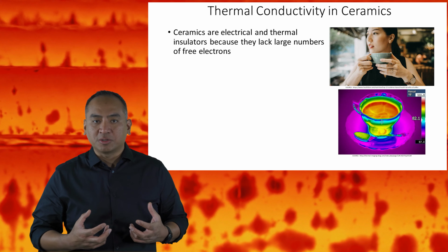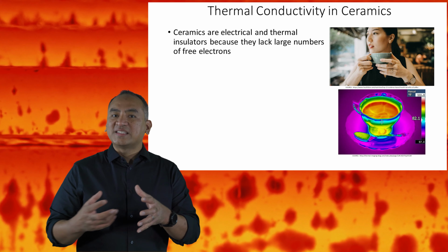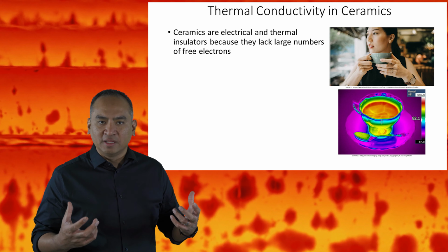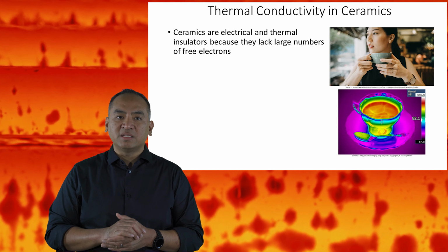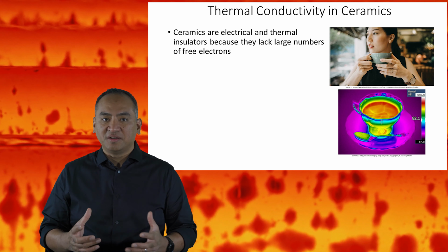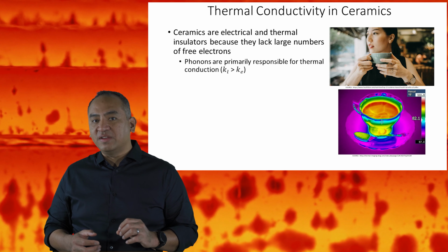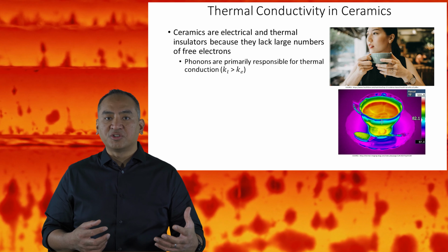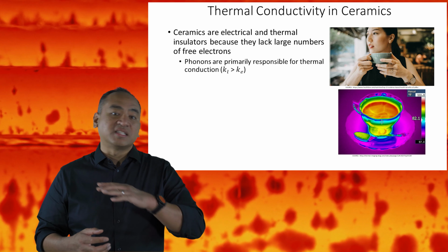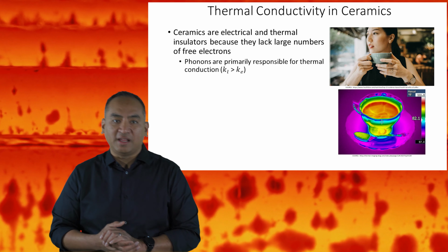Ceramics are electrical and thermal insulators because they lack large numbers of free electrons. In ceramics, phonons are primarily responsible for thermal conduction. Thermal conductivity has a phonon contribution and an electron contribution. And in ceramics, this phonon contribution dominates.